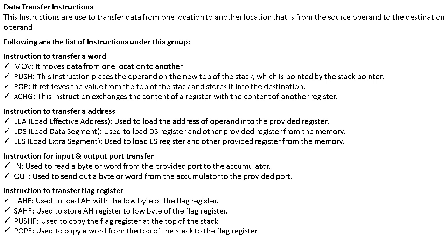Instruction to transfer an address. LEA, load effective address, used to load the address of the operand into the provided register. LDS, that is load data segment, used to load the DS register and another provided register from the memory. LES, load extra segment, used to load the extra segment register and another provided register from the memory.